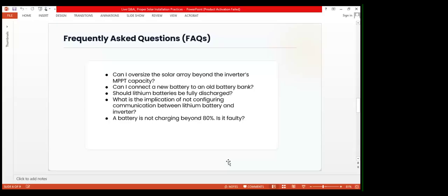Not advisable in series at all, because one battery will be there not working. Either the old battery will quickly charge up and get disconnected, or get over voltage, because you are connecting in series, and the new one wants to take higher current, it will push more voltage across the old one, and then it will get overcharged. Meanwhile, it's in series with the other one. So it is not advisable. It's unprofessional to do that.